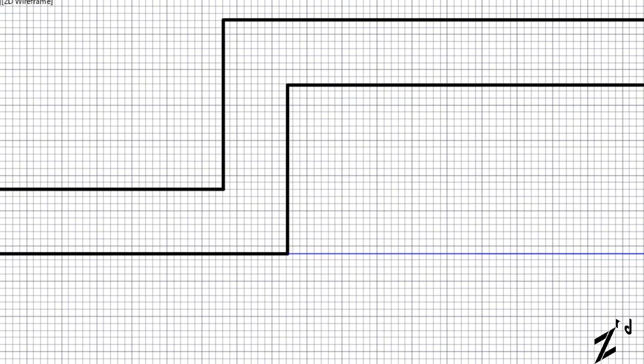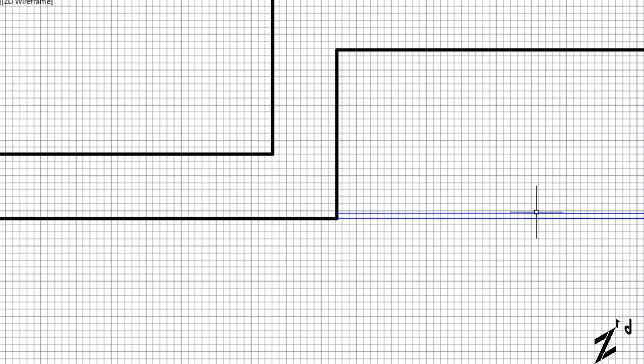Let's assume that we use 19 mm ply here, sorry, 1.9 cm. So those are our doors, and let's say we want to divide this by 3. So let's say div 3, enter, line 1 point, there's the other point here. So we have 3 doors, right?